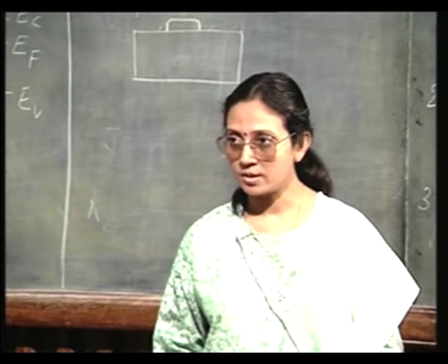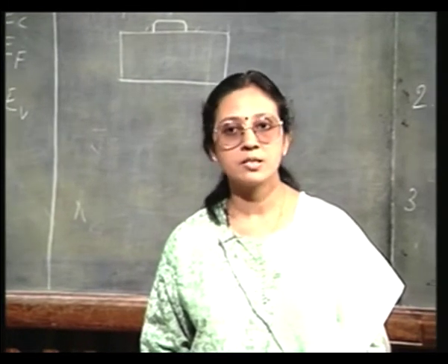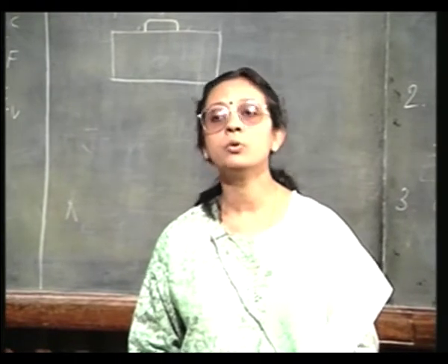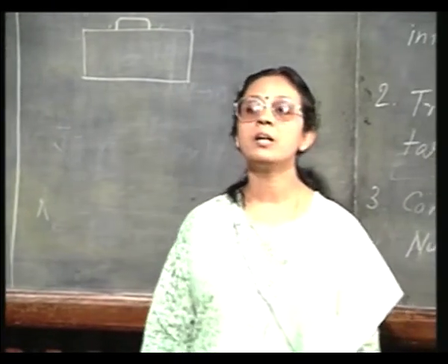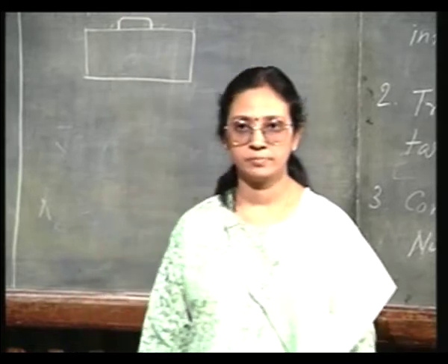In the in situ technique we use a quartz crystal thickness monitor. There is a quartz crystal which is used as a thickness monitor. Now, you know the quartz crystal will have a resonant frequency.